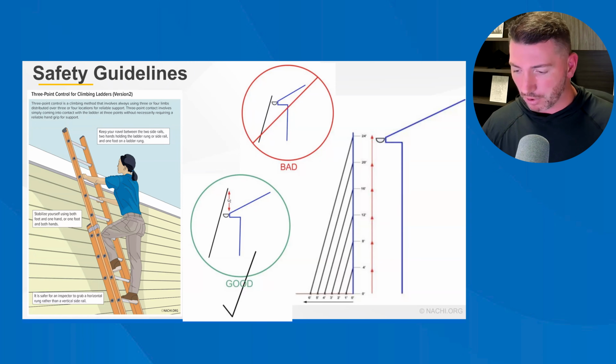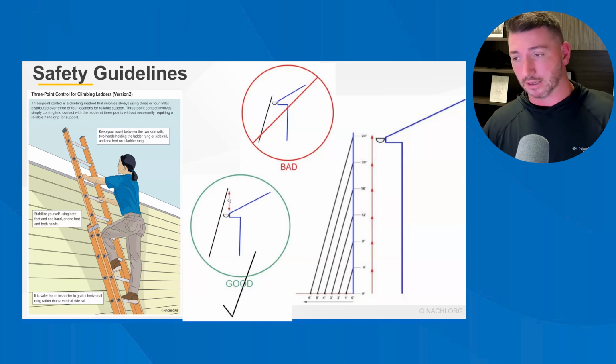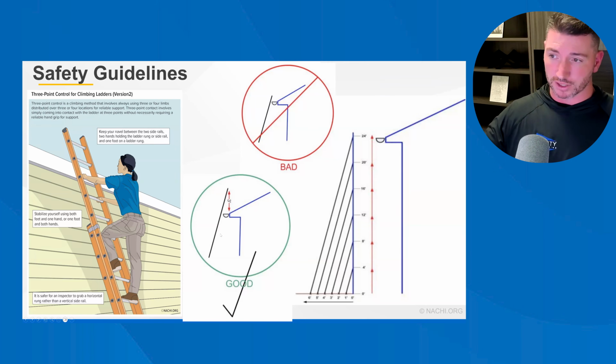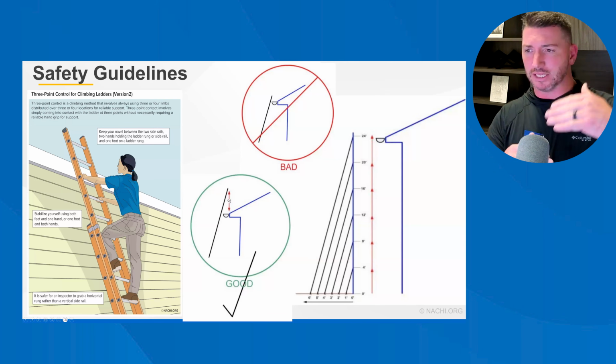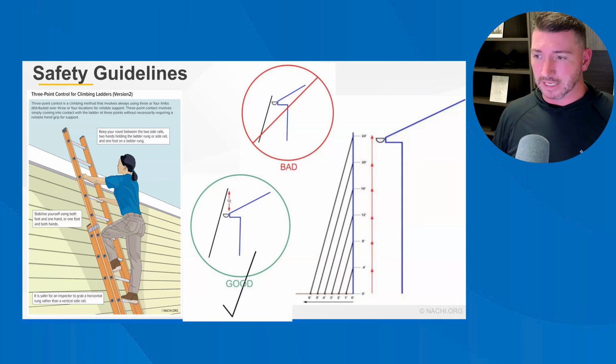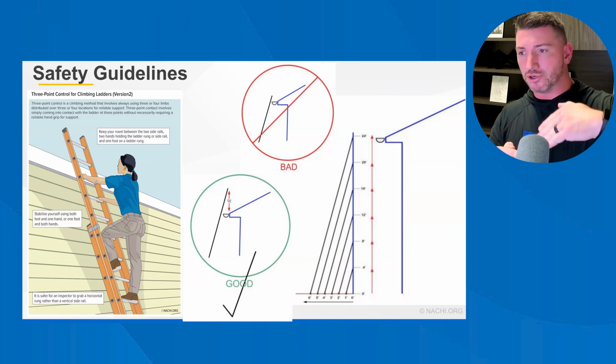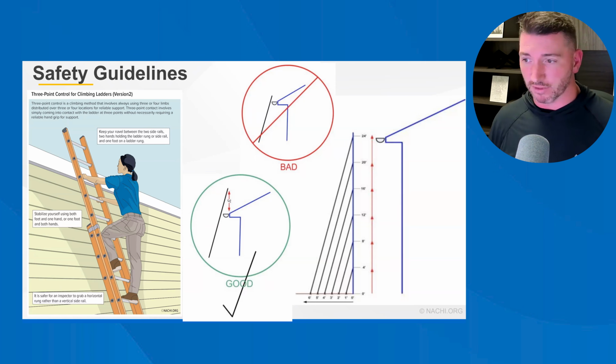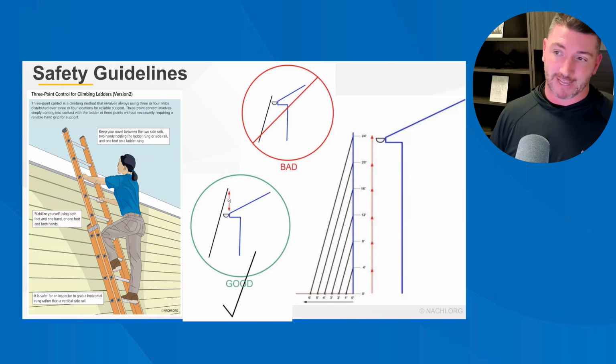If you have to step around a ladder because of the rungs, technically, as shown in this example, 3 feet or 3 rungs, the top rung is, I think, 6 inches, and then every in-between rung is a full foot, and then the bottom rung is 6 inches. So with those normal rungs, you should have 3 rungs above the access point. Now, technically, in this illustration, this inspector only has 2 rungs above the access point. That is technically not correct. I would prefer it how she has it, but 3 rungs, 3 feet is what they want to see.